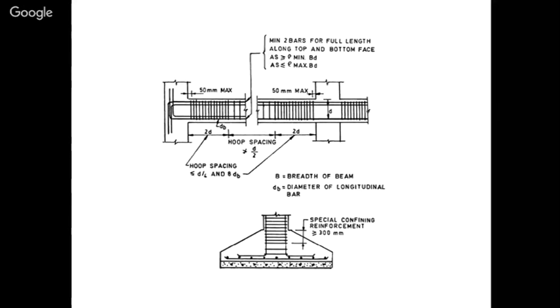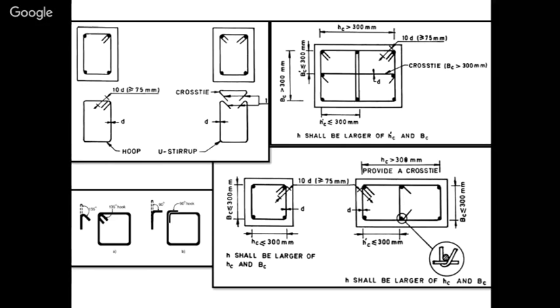That's why we recommend closer confinement at the foundation level. So these are the various detailing requirements for how that confinement should be made, the hook inclination as well as the hook length. Because if it does not have a proper hook, what will happen when a large deformation occurs? The confinement will open. When the confinement opens up, it can't confine the concrete, so it will immediately rupture and fail.